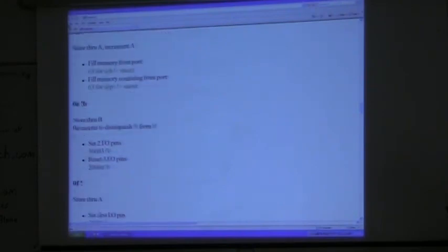Here's a store B, which does not increment, but it does store into the address loaded into the B register. The B register is only 10 bits long. It isn't a real number. You can't read it back. The A register is 18 bits long and you can read it back.